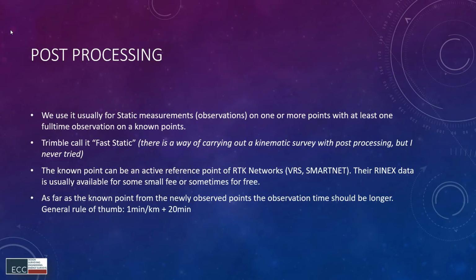The other thing is that you don't need a good internet connection. Usually if you can't use VRS, you use this method to survey, to do some control points. I don't know why you can't use VRS, maybe because the internet connection is bad or very weak, you are at the edge of the country, or something is not right.